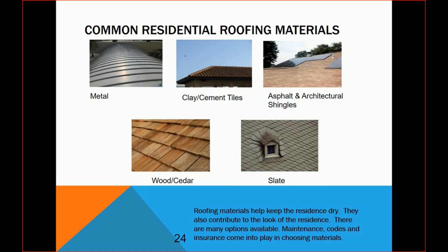Clay and cement tiles, again, those are very heavy tiles. They're really good for places like in Arizona and stuff where it gets cool at night, so that clay will hold in the coolness and help cool the house during the day. They make manufactured clay and cement tiles that look like that but don't have the weight associated with them, and they would not also have the characteristics of that. But if you wanted that style, you could get that style and not have to have a much stronger structural system, etc.